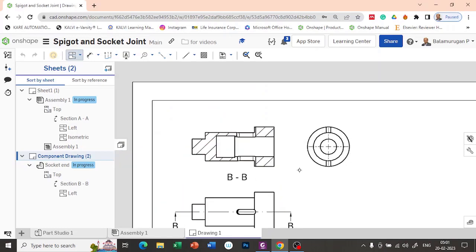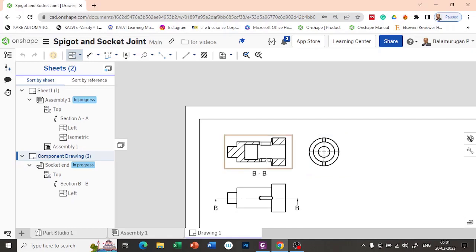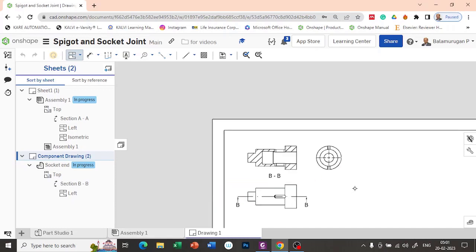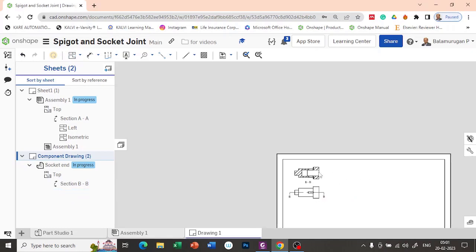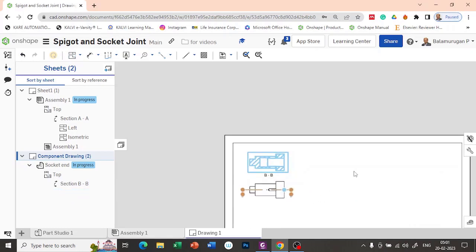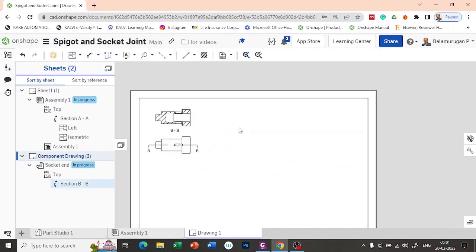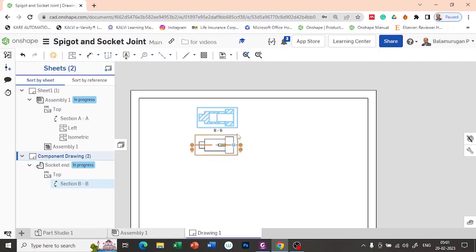You can select the side view. So if you want to provide the side view on the opposite side, that is also okay. Whatever view you want to create, you can do it. For example, if you want to create the right side view, the view from this direction, just move your parent view. Automatically all the other projected views from that view will be moved accordingly.